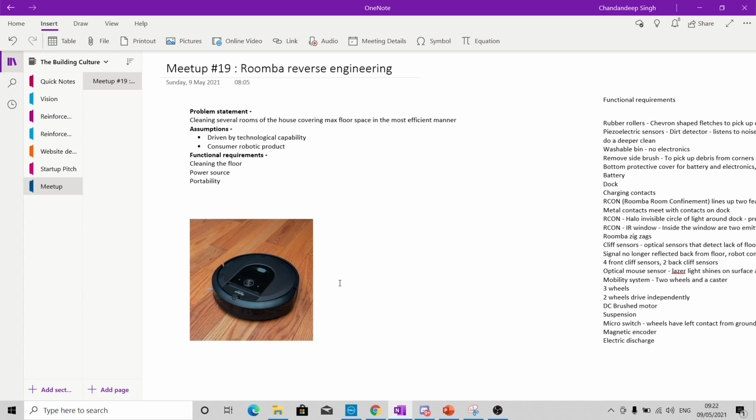It should not fall off when there is an empty space. It should first of all have collision detection, so it knows when it collides. And second, it should not fall off when there is no ground, for example a stair or some step.